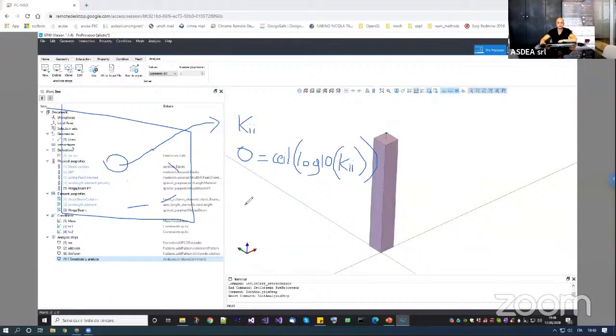So when you have the order of magnitude, the penalty parameter should be equal to 10 to the power of this order of magnitude plus 8. Why 8? It's not just a magic number. In computers, a floating point, which is a real number, is represented with 16 significant digits. So it cannot be arithmetically exact. There is a finite precision for floating point numbers, and 16 is the number of significant digits.